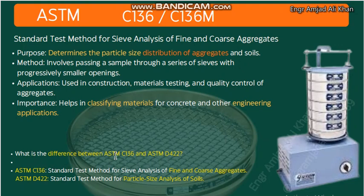What is the difference between ASTM C136 and ASTM D422? The main difference: ASTM C136 is the standard test method for sieve analysis of fine and coarse aggregate. We conduct C136 on fine and coarse aggregate, and with D422 we conduct particle size analysis of soils.